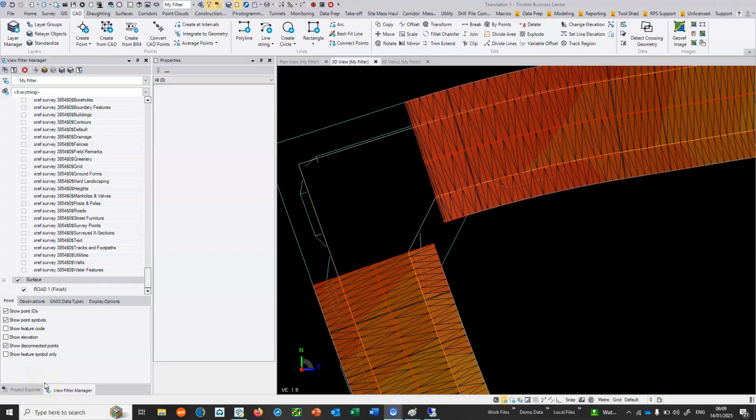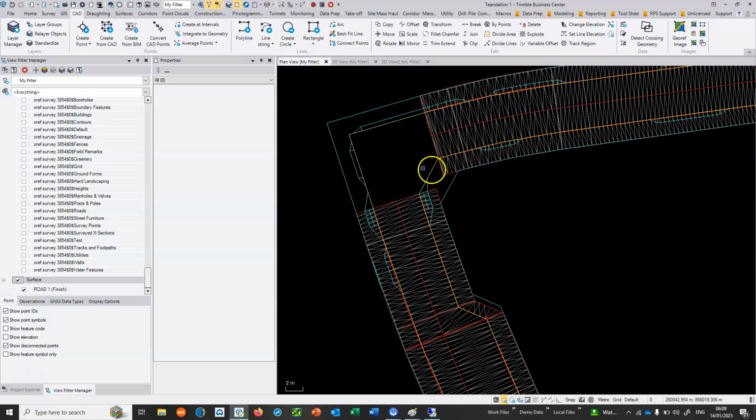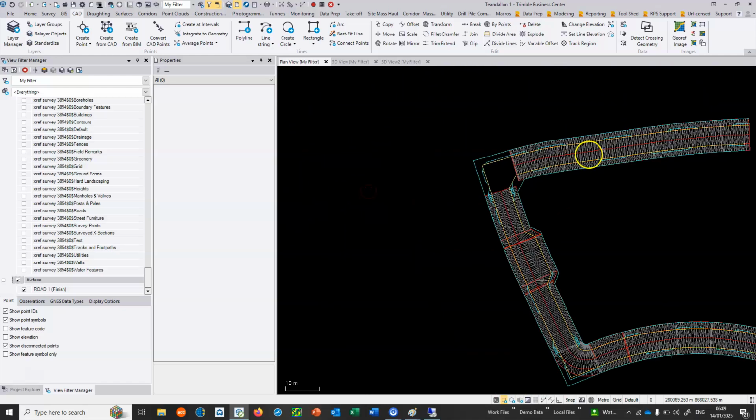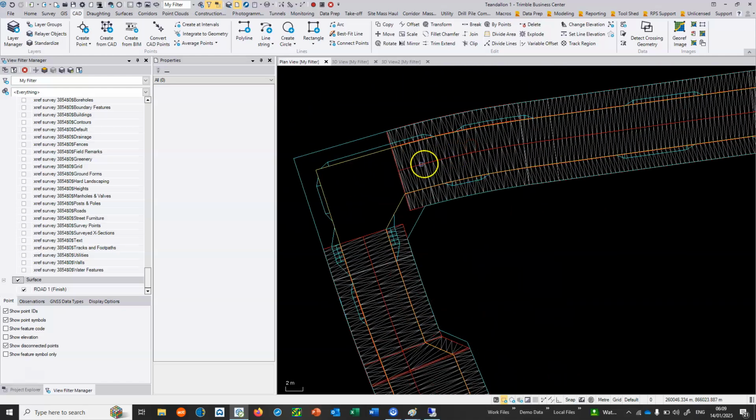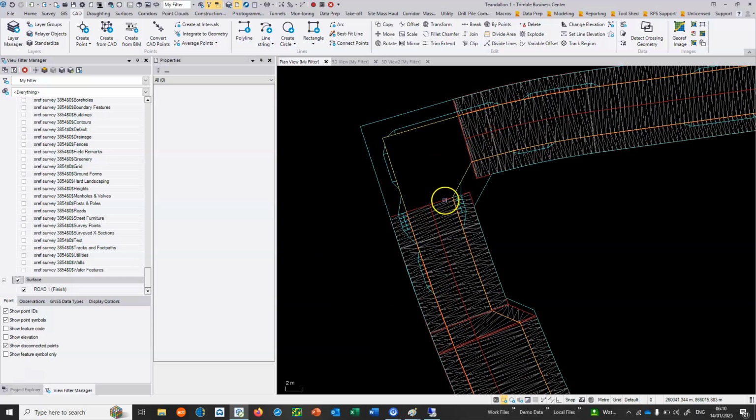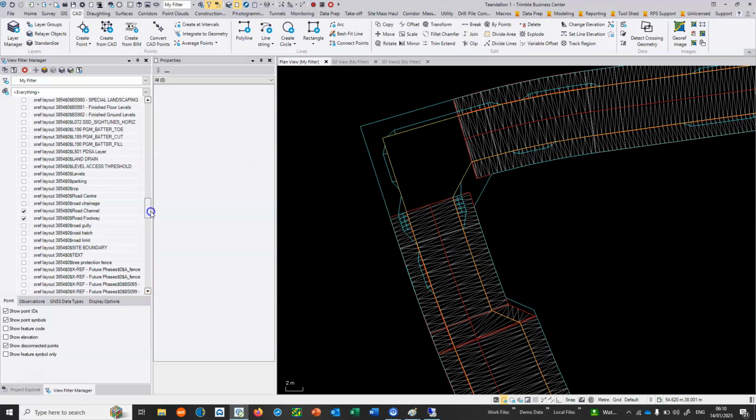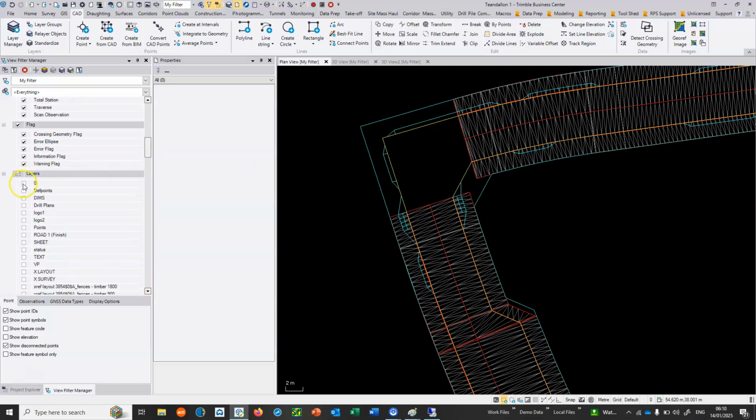Across the industry, we're seeing more and more road designs which don't conform to a traditional template-based road design and therefore cannot be modelled in that way. In this example, we see a very traditional road design going up this part of the road, and then a right angled turn. The alignment actually has a conventional curve in it, but we've got a right angled turn on the curb, which basically will not model properly with a template based design.